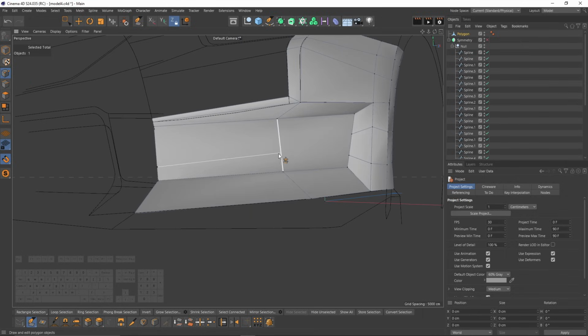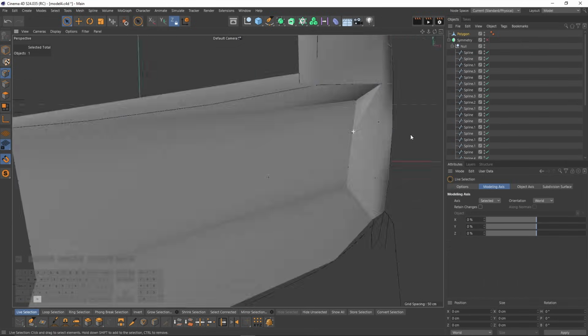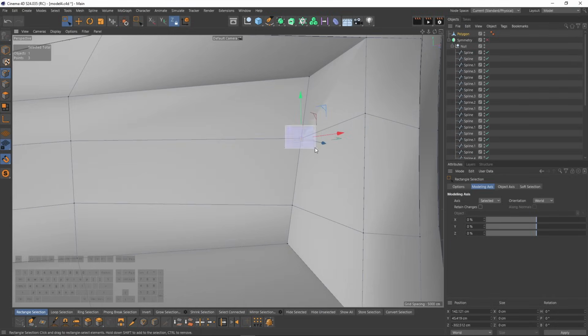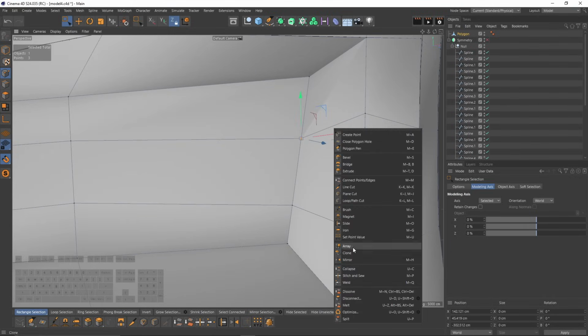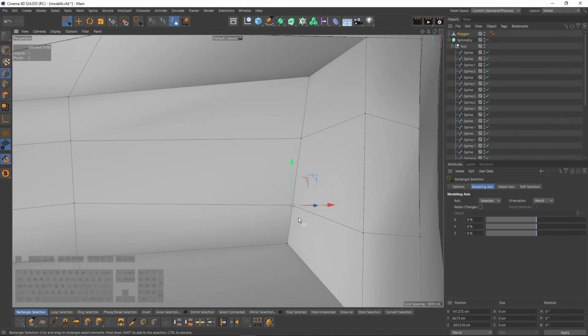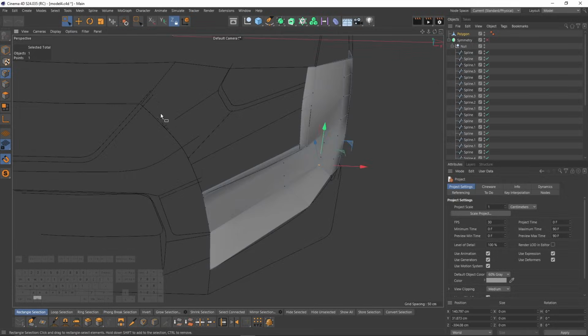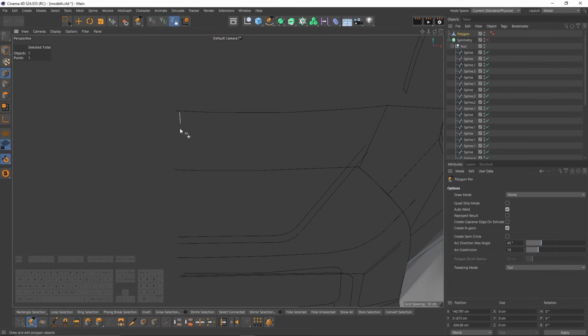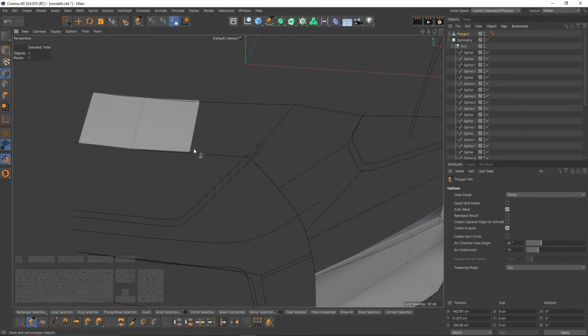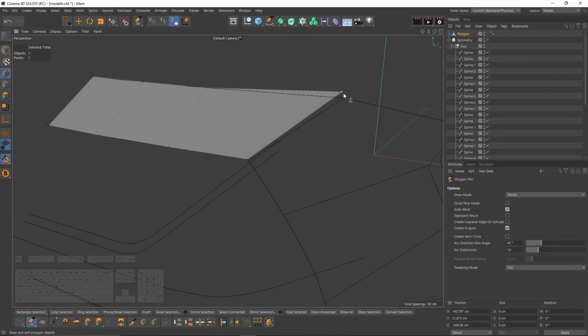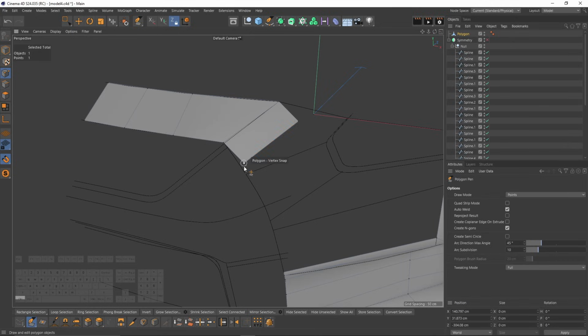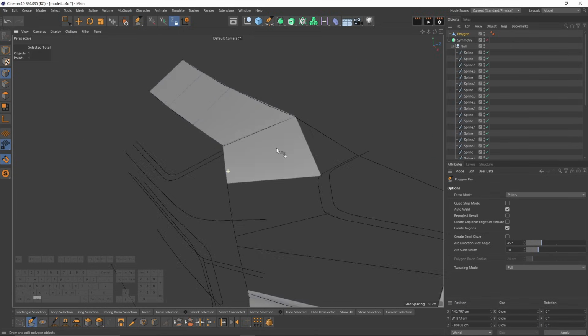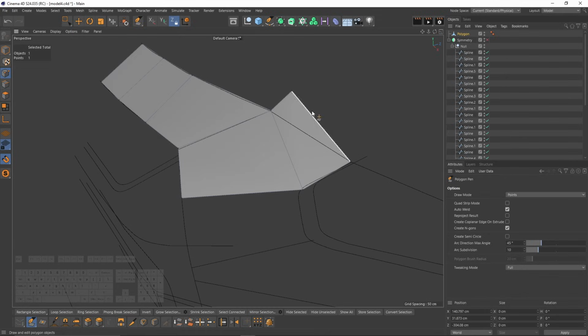Now I am gonna create these edge cuts. I need to weld these points, which I have 3. Right click, select weld, if I can find. Yes, here. Also that one. Now let's switch here. Click on the splines, create a new polygon. After that, extrude that edge, another one. One more time. Then I am gonna close here.